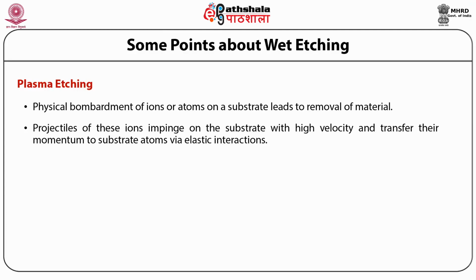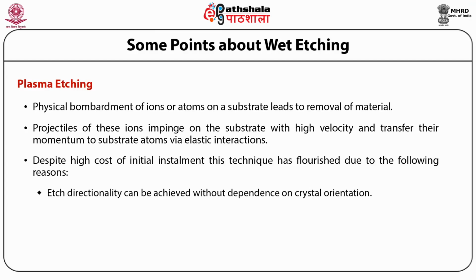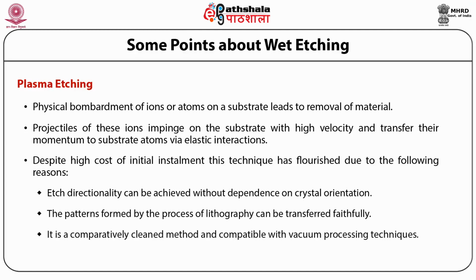Plasma-assisted etching has been rapidly used in recent years. Despite the high cost of initial installments, this technique has flourished due to the following reasons. Etch directionality can be achieved without dependence on crystal orientation. The pattern formed by the process of lithography can be transferred faithfully, and it is a comparatively clean method and compatible